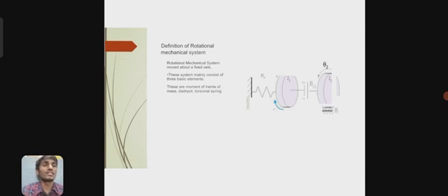And we can consider three elements, a dashpot, a spring and a torsional spring, which affect the resultant torque about this free body. Here K defines the stiffness of the spring, B is the torsional dashpot, M is the mass of the body, and T is the torque applied on the body, where θ2 and θ1 denote the angular displacement of the body.